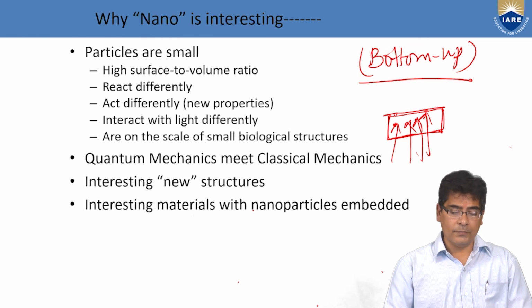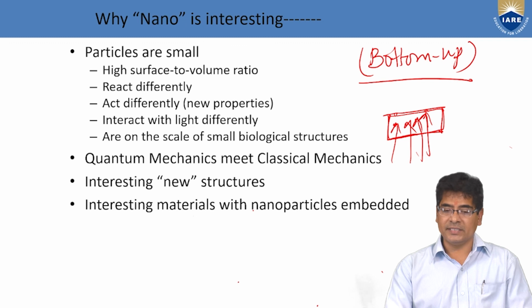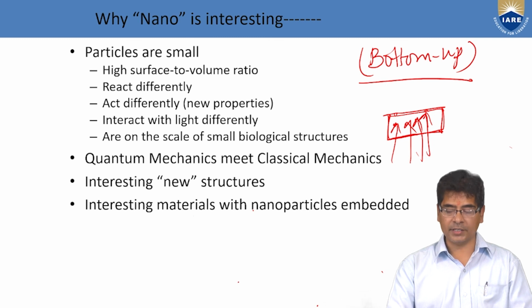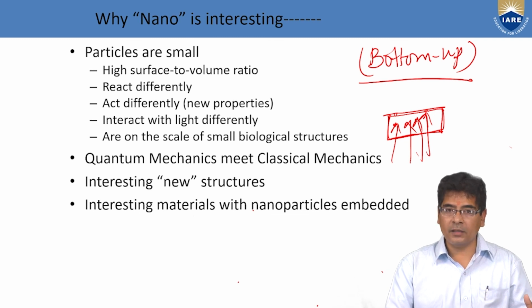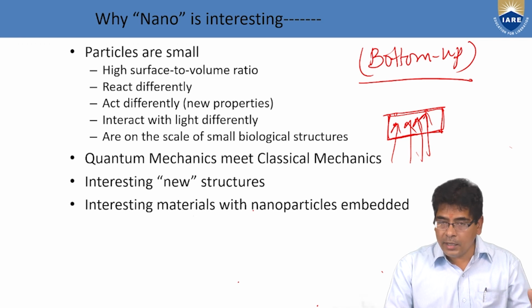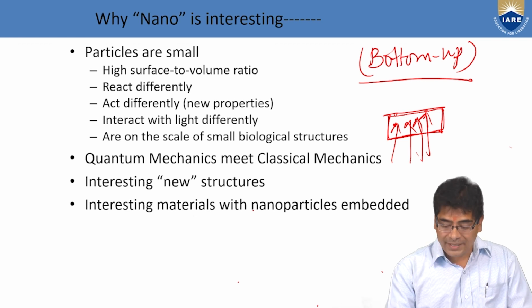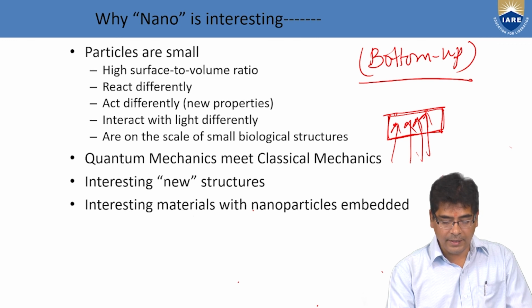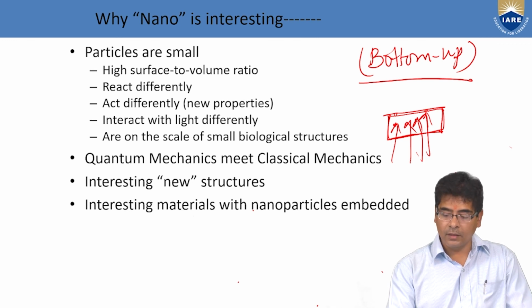These PVD methods differ in the means for producing the metal vapor and the details of plasma creation. The primary physical vapor deposition methods are ion plating, ion implantation, sputtering, and laser surface alloying.